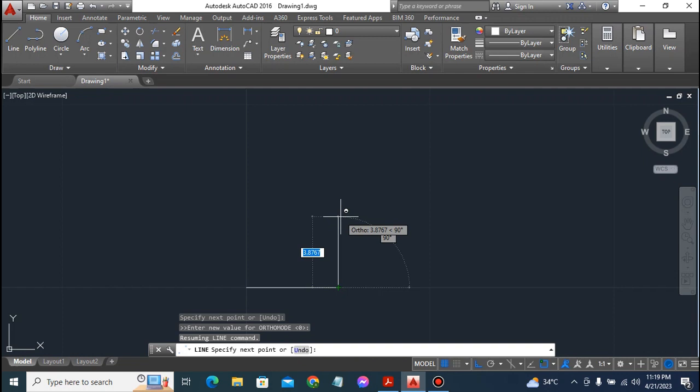Press shift and 3 so that ASCII comes up. Then you type in your coordinates 105,102. Enter, and that is our point C. So we make progress to locating or plotting point D.